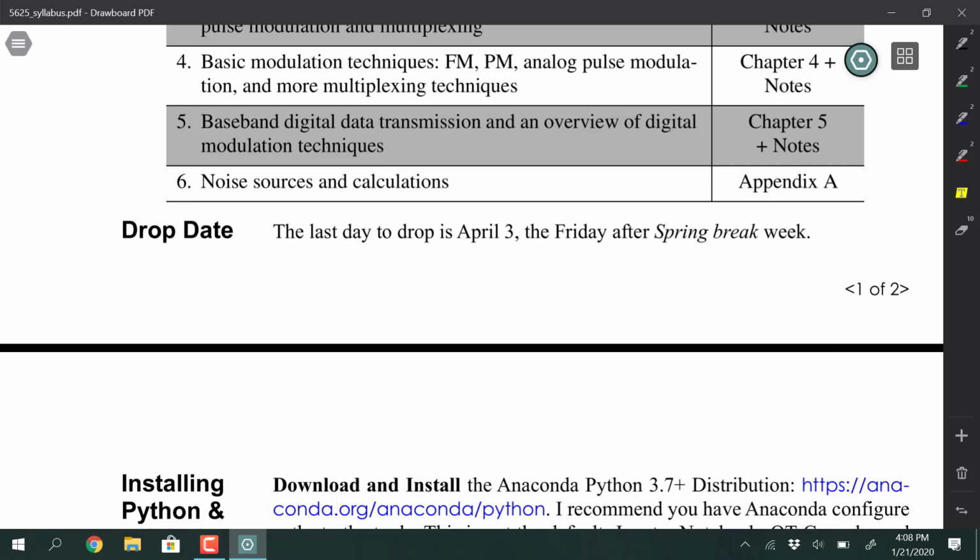But there are some basic digital communications ideas. I did quadrature amplitude modulation in the project last spring, and then I had convolutional encoding and decoding in there. Then I had the PCM encoding and decoding, so you could take a speech vector, PCM encode it, send it as bits, protect the bits with a forward error correction scheme, and so on and so forth, and simulate, right in Python, a complete digital communications process. My hope is that that will now be able to take place right on the Pluto, transmitting and receiving.